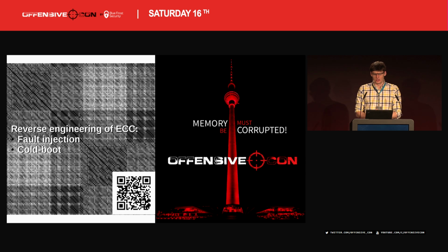Indeed, the host that we chose has 128 bits per ECC word, and we used it to reverse engineer a machine that has 64 bits per ECC word. This was a difference that we observed while reading the data, so we had to cope with it by doing the proper equation and computation. But this is easy to spot. It requires some work if there's a complete mismatch between them, but you can still get around it. Okay, thanks.